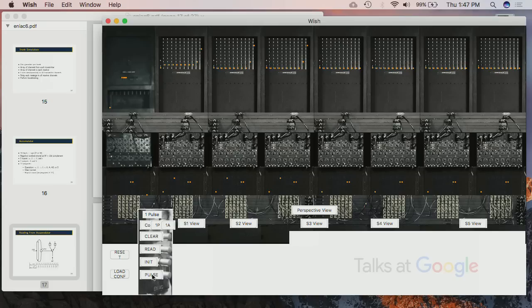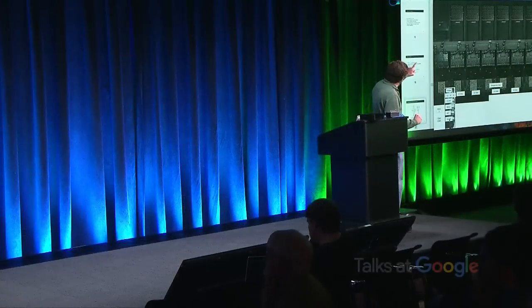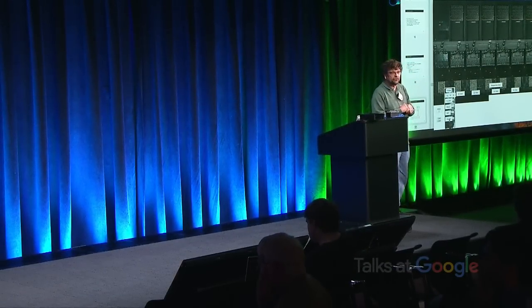So here, if you look at the one on the left, all of the positions have moved up 1 spot. That's 1 of those 10 pulses. And as we're going through those 10 pulses, you see that some of the things are also causing things to climb on the other 2 accumulators. And the lights underneath are the carry lights. So they tell you when it's going from one to the other. Once we've resolved all of the carries, we now have in the second accumulator a sum of 42, and in the third accumulator the difference of 12.